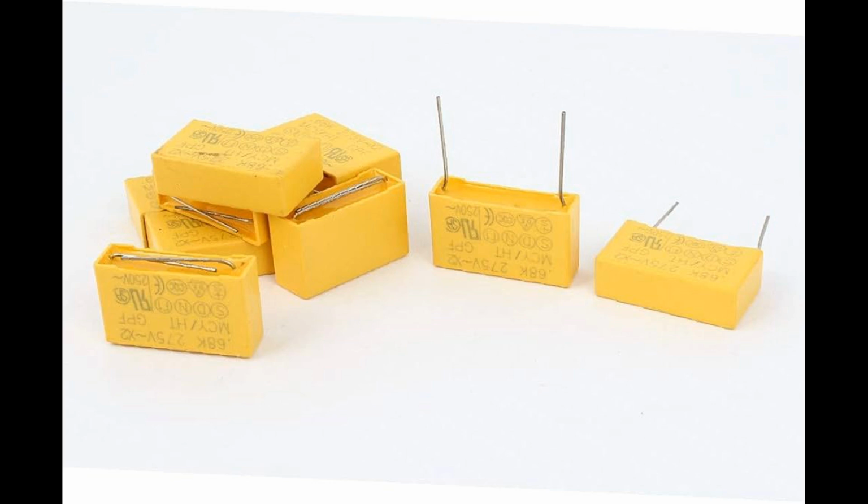In self-healing capacitors, usually metallized film types, small dielectric breakdowns caused by high voltage automatically heal. The metal layer evaporates around the point of breakdown, restoring the insulating properties without significant loss of performance. Axial or radial leads. Film capacitors may have leads or pins for mounting on circuit boards. Radial leads come out from one side, while axial leads extend from both ends of the capacitor.